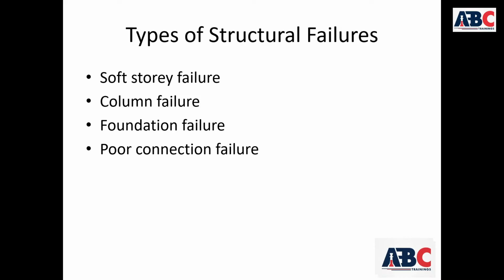Next point is foundation failures. Foundation failure plays a very important role in seismic performance. During an earthquake, foundations may fail due to soil liquefaction, uneven settlement, insufficient depth, poor soil bearing capacity.